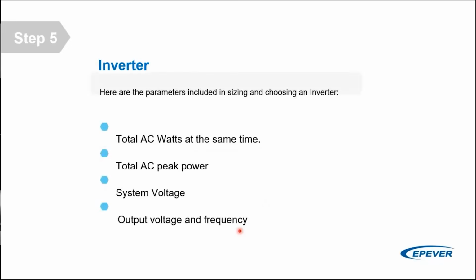And you just have to consider that it's better not to use the inverter at its maximum capability. So while I need, for example, a 3K or 4K inverter, it's better I choose a 5K, because not using the inverter at its full capacity helps it be more efficient. So always take into account, for example, 25% over rating for the continuous power of the inverter.